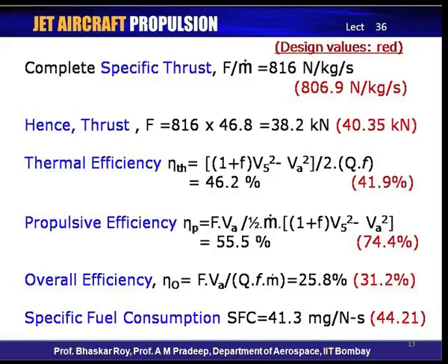So, we have estimated the off design performance of the entire engine, and it tells us that overall efficiency is lower than the design point efficiency, the thrust is lower than the design point thrust, but some of its other figures of merit, the specific thrust is good, it is actually marginally higher than the design point, and the specific fuel consumption is indeed actually lower than the design point specific fuel consumption.